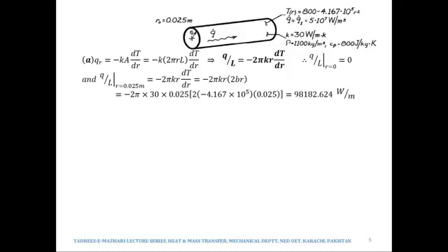Suppose that you are at the center of this cylindrical rod, and then you try to reach the outer surface. So you will move radially, you will move out in the radial direction. Therefore the area that the heat will be incident upon is in fact 2 pi rL. So if we now take this length into the denominator of Q, the right hand side would be minus 2 pi kr times dT by dr.